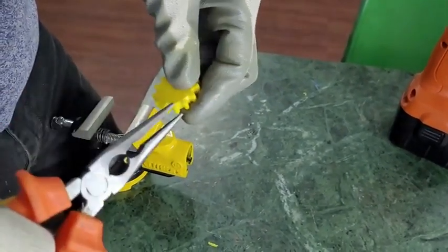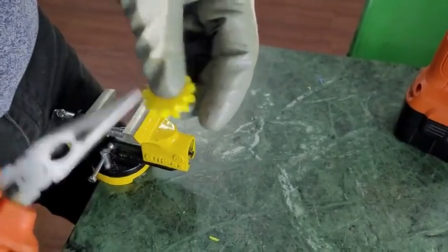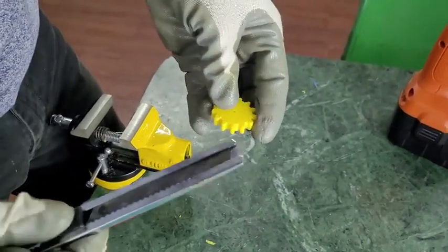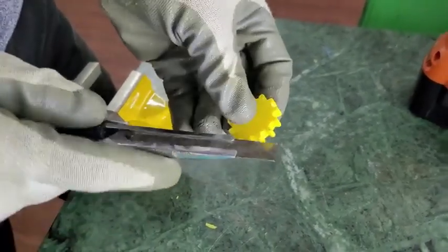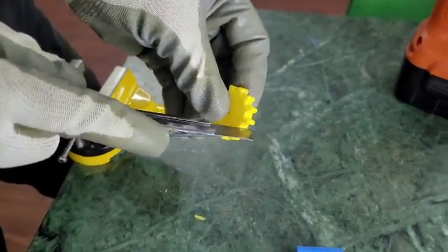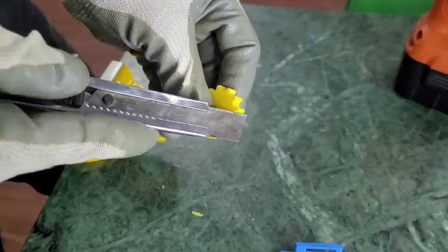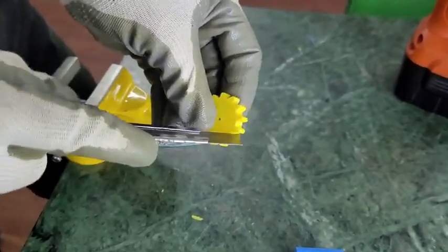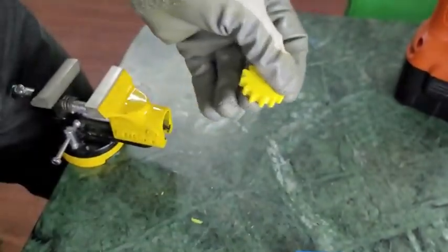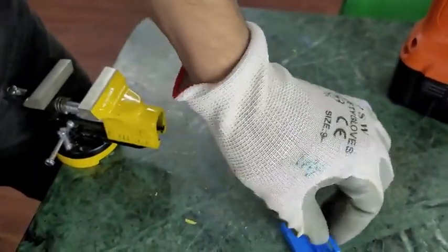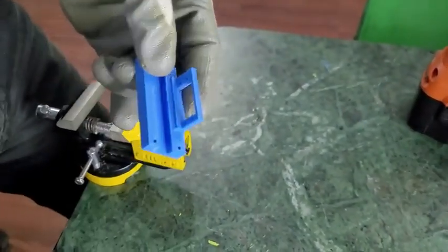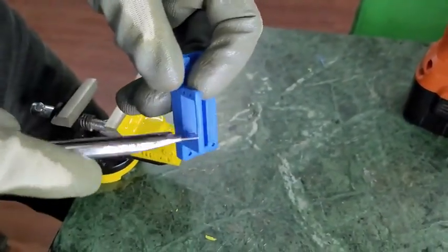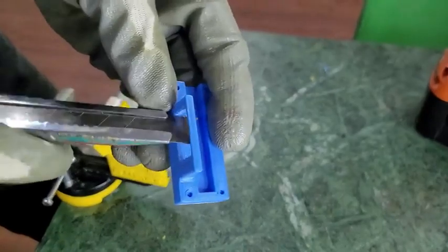but now let's take some extra sharp edges out of the 3D printed parts just to make sure that all the edges are smooth and there is no burr, so that our mechanism works smoothly. Use a paper cutter if needed to remove the extra sharp edges. Since the 3D printed parts are secured onto the 3D printer table, the base plate, they usually have those edges. So take out those sharp edges on all the parts using a paper cutter, and if needed, long nose pliers.